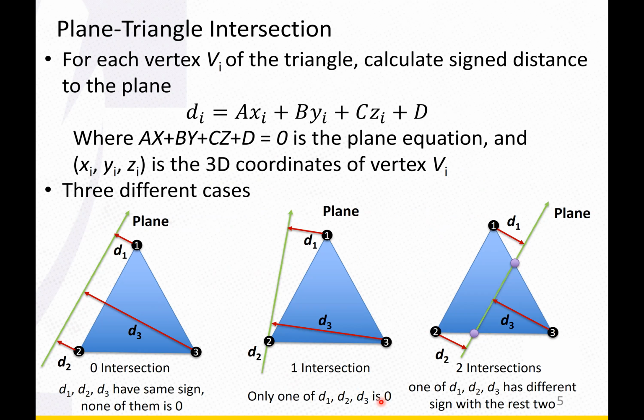And again, that will slow down the whole process. So these are all issues for these plane-triangle intersections: the numerical issue, the rounding errors, the density issue. If the mesh density becomes high, that will slow down your process. And also, if you have smaller layer thickness, the efficiency will be a problem and the robustness will be a problem.